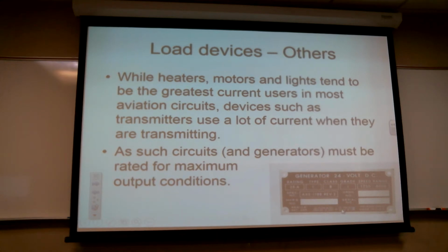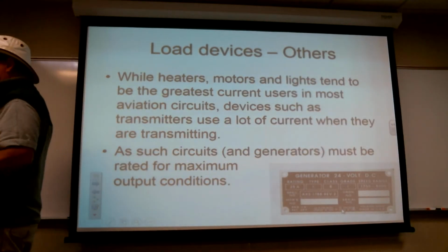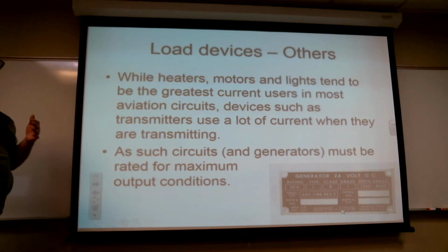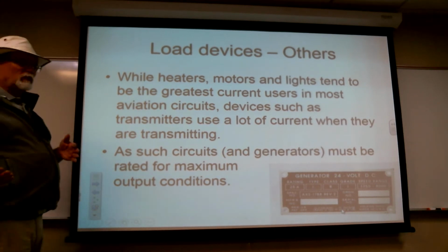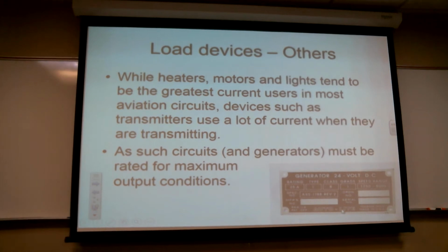Typically, light bulbs, as far as I know, as a group, are the only thing that are directly rated in power. They'll say it's a 21 watt or 60 watt or 100 watt bulb. They'll then also tell you what voltage it's designed to operate at. That's sort of a departure from the norm. All other components out there are rated in volts and amps, for which you could get to the power fairly easily just by multiplying them.